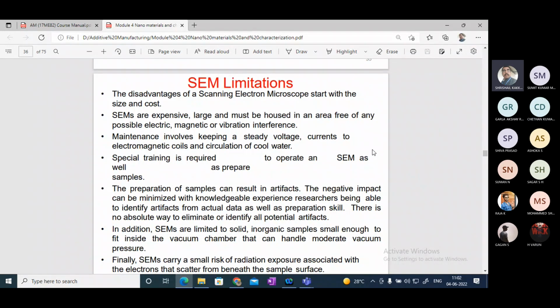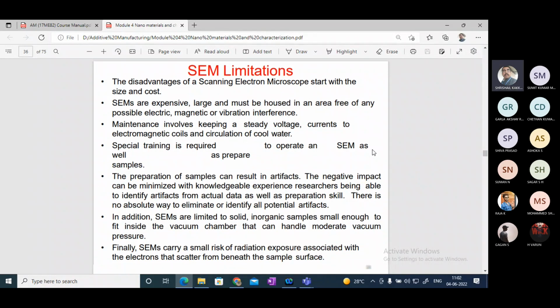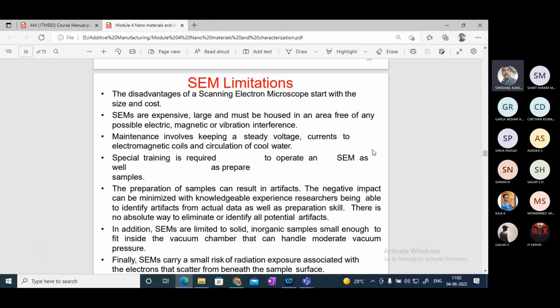In SEM, the scanning electron microscope, the beam will not be transmitted through the workpiece. The electrons falling onto the workpiece for testing will not enter it. Instead, they will scan it. The electrons bombarded over the workpiece will be reflected by the test piece, and these electrons will be attracted by a detector. They bounce back, and these will be converted into the required pixels of the figure.